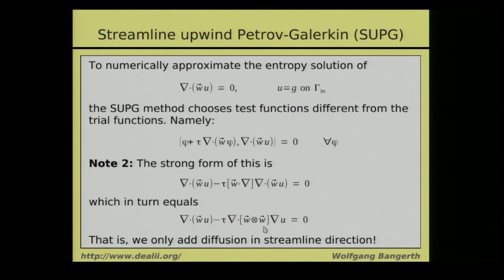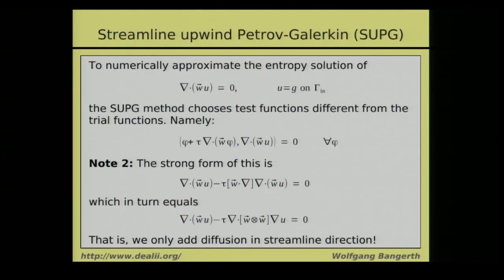And so this is sort of a slightly refined version of the isotropic artificial diffusion that I had on the previous slides, where I really allow diffusion only in a subset of directions. And it turns out that that is enough, that I get a stable solution through this process as well. So this streamline diffusion process is enough to yield a stable solution.